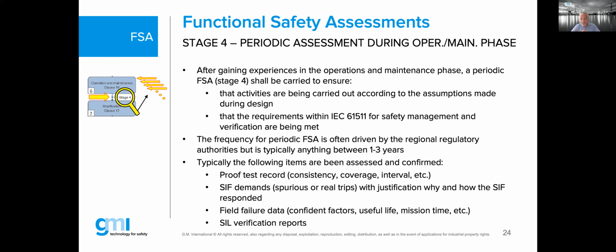That is one thing. Typically, if I would go in, and now thinking loudly, I would like to see, first of all, their proof test records. How can they prove how consistently they have carried out those proof tests on their safety instrumented functions?